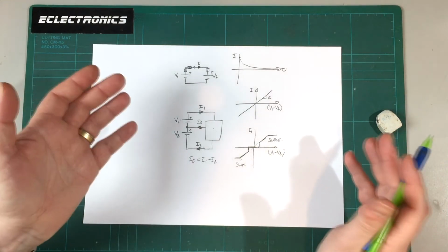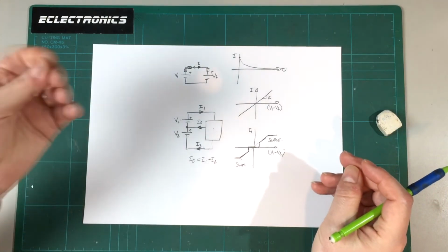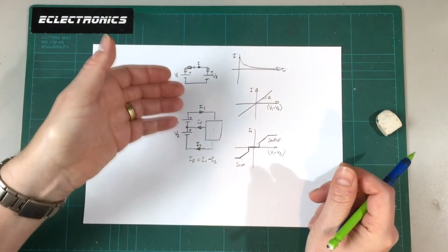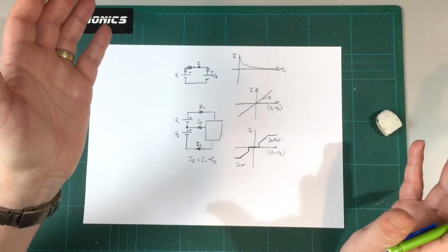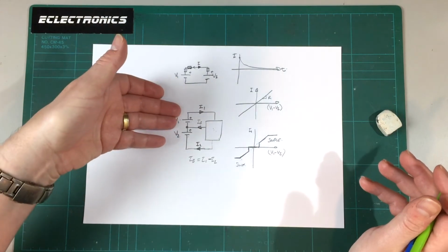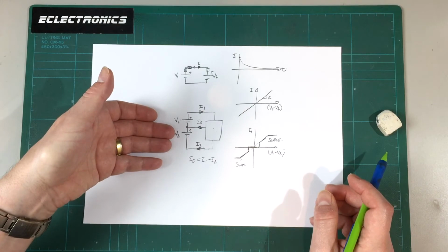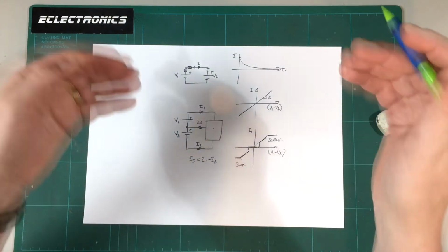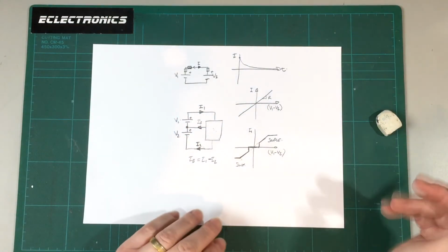Of course, now we also have on eBay these capacitive charge balancers. So instead of using an inductor to store energy and then transfer that charge over, you charge a capacitor up from one cell that's got a higher potential, and then presumably, I don't know if this is how they work, but I'm assuming the case, connect that capacitor that's now charged to V1's voltage that's higher, you then connect it to V2, which has got a lower voltage, so current will flow from the capacitor into that cell until the two equalise, and then you repeat that cycle repeatedly. So you charge transfer using a capacitor as the storage element.